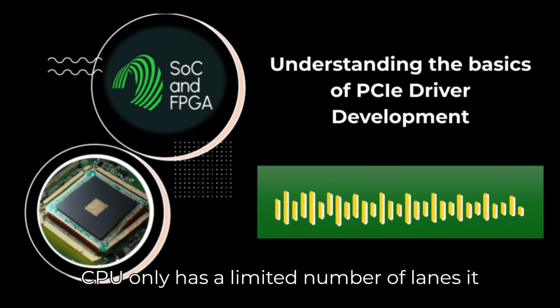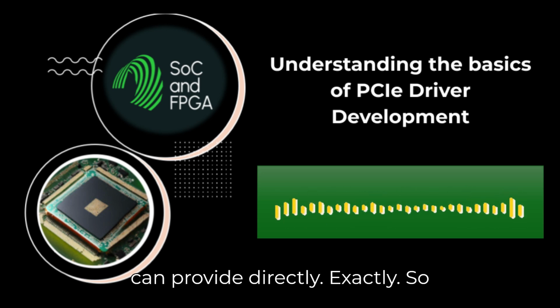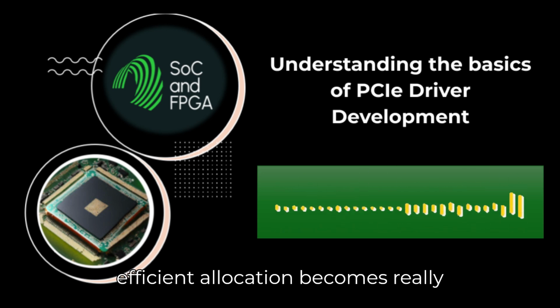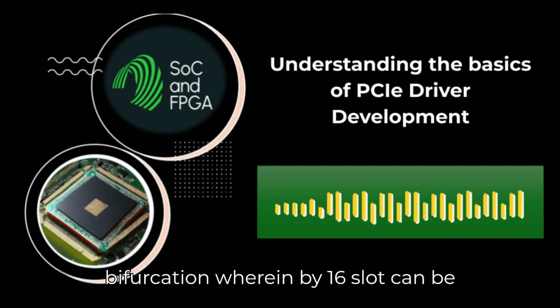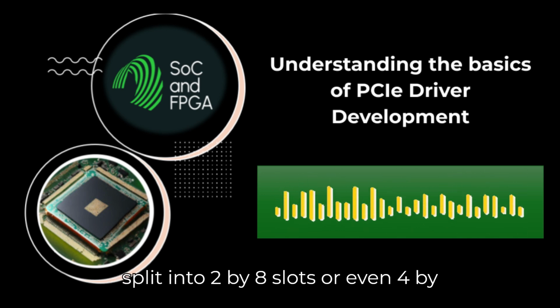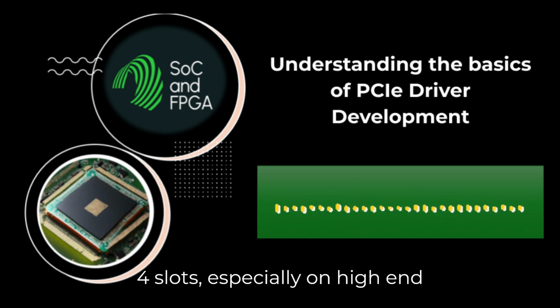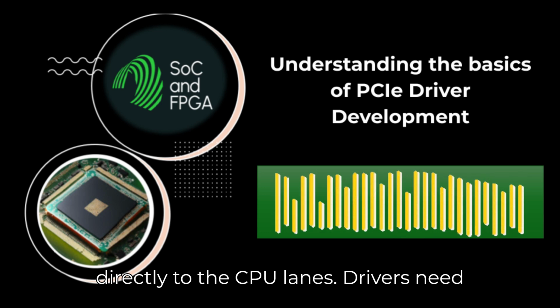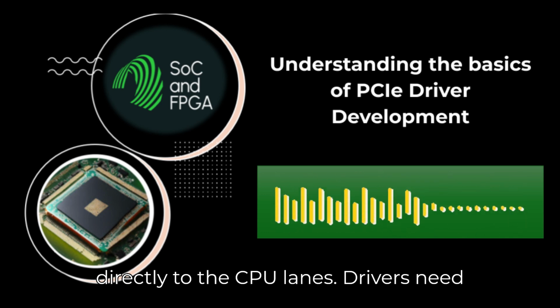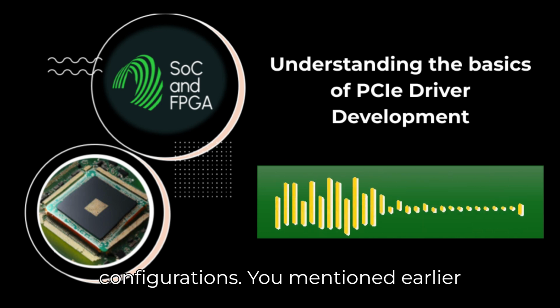Right, because the CPU only has a limited number of lanes it can provide directly. Exactly. So efficient allocation becomes really important. You see things like lane bifurcation, where an x16 slot can be split into 2 x8 slots, or even 4 x4 slots, especially on high-end motherboards, to connect more devices directly to the CPU lanes. Drivers need to be aware of these possible configurations.